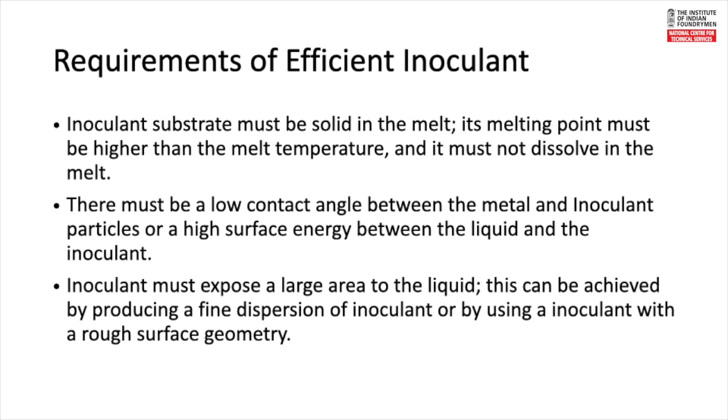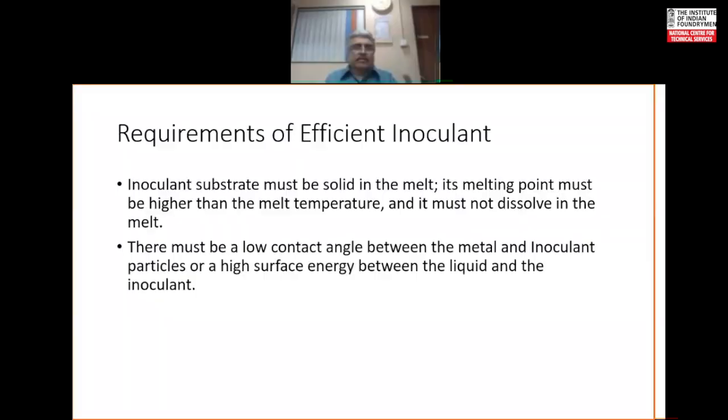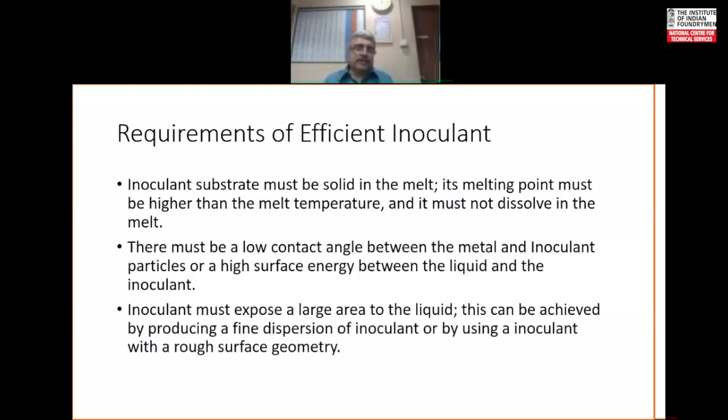It is not as if it will never dissolve, but it will dissolve slowly. There must be a low contact angle between the metal and inoculant particles. That means metal should be able to wet the inoculant particles so that the effective nucleation can happen. The carbon atoms can get deposited onto the surface of the inoculant particles. Inoculant must expose a large area to the liquid.